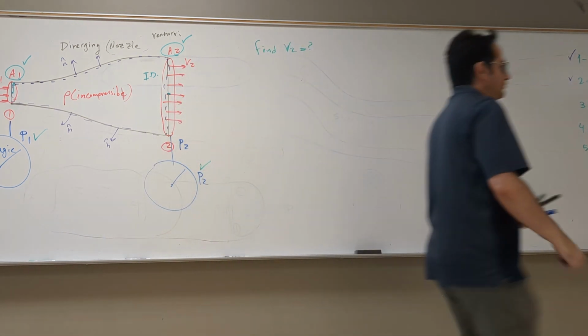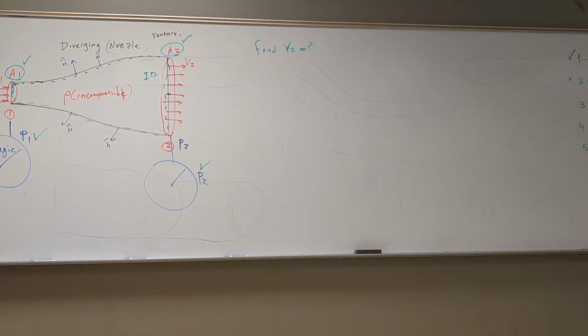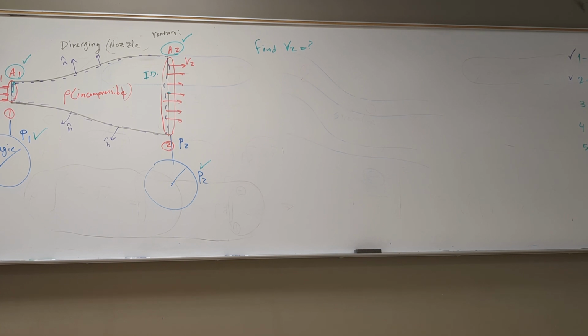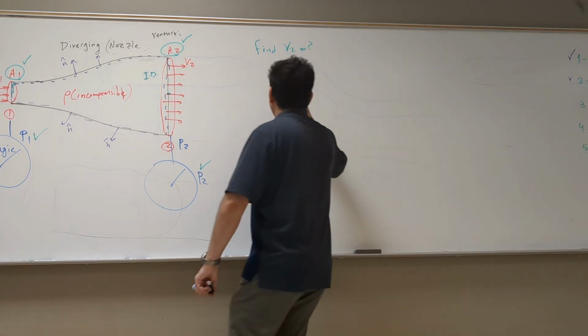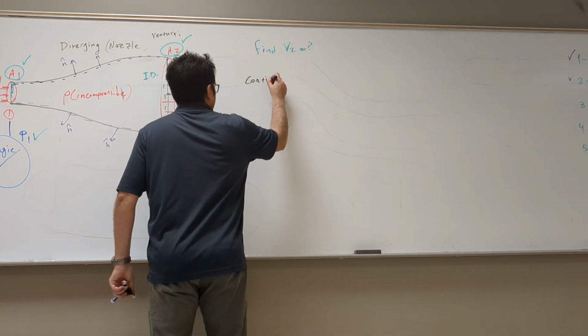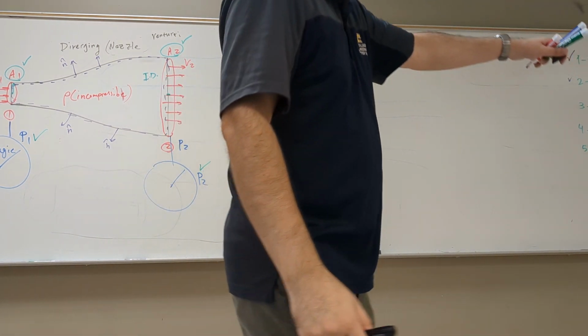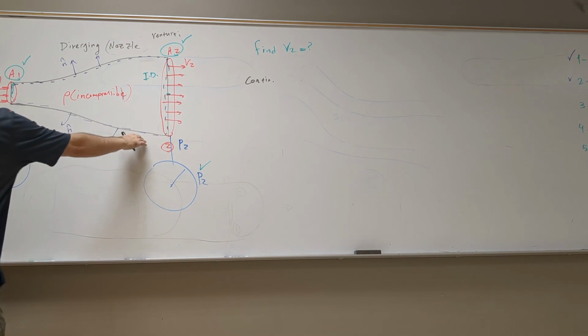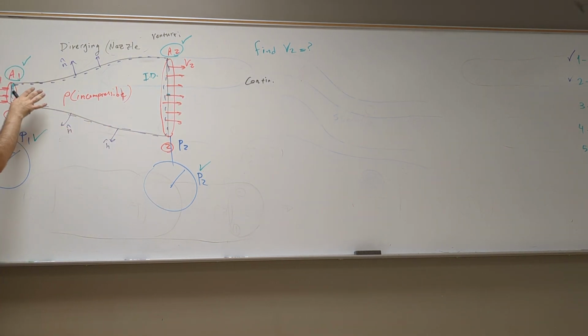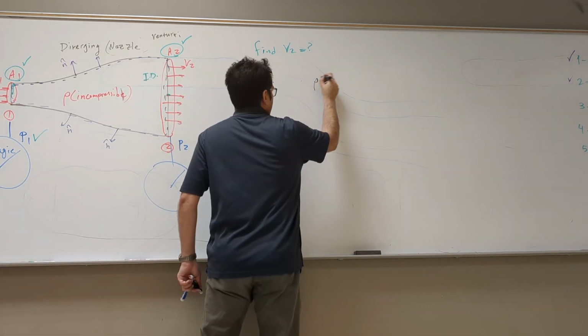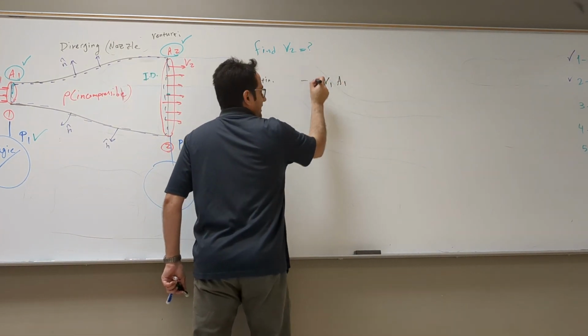Am I going to write these 2 equations and solve it? They are already done a bunch of derivations. So just write momentum and continuity. The first one, continuity. If you expand that integral over the spaces, this gets 0. The surface is 0. Here you get rho v1 a1, positive or negative?